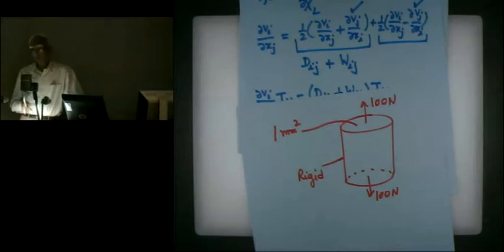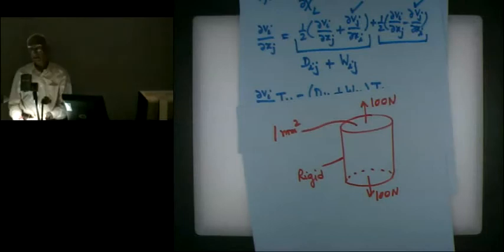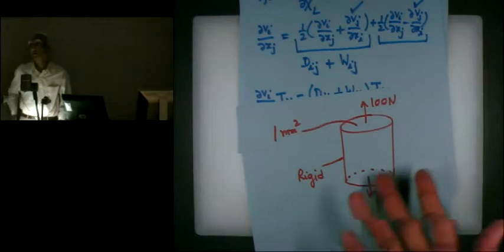And there is only one component of stress because of this loading. What is the strain induced in the body? I would say 0. Because the body is rigid. So there can be a stress even though the strain is 0. The stress has nothing to do with whether there was strain induced in it or not. The stress has something to do with the loads applied.